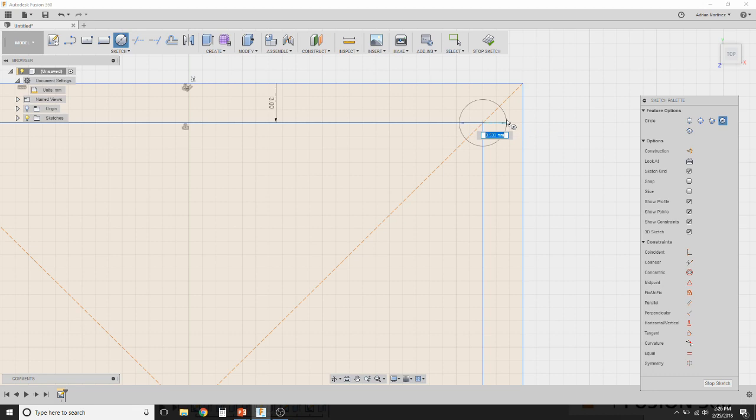And really to have good strong walls, to prevent the walls from bulging or turning white, the plastic can sometimes turn white if it's stressed when you thread a screw in, you want to make sure you have a consistent 3mm wall. So you definitely don't want to locate your screw here. So I'm going to hit escape.